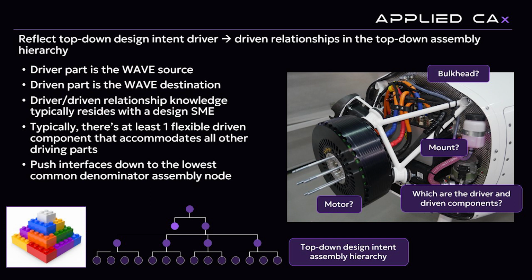In this case, if you're purchasing the motor but designing the mount, the mount is the driver and the motor is driven, so it'll change position based on what you're defining. And there's usually at least one flexible component.